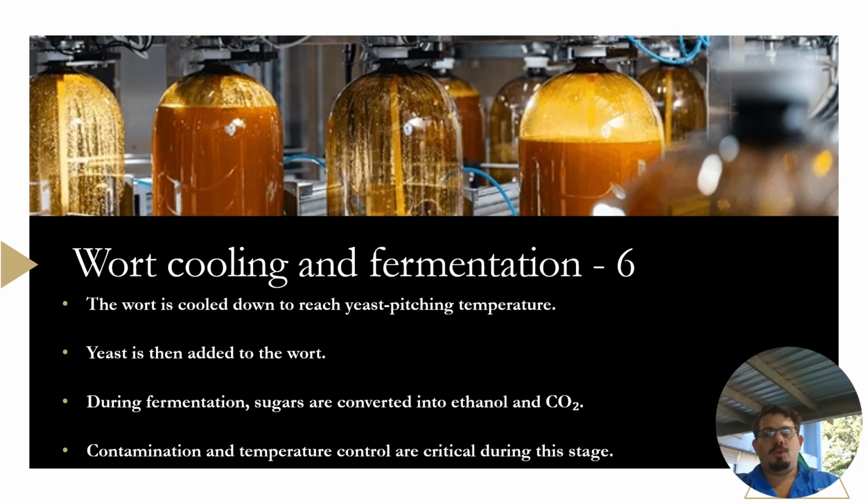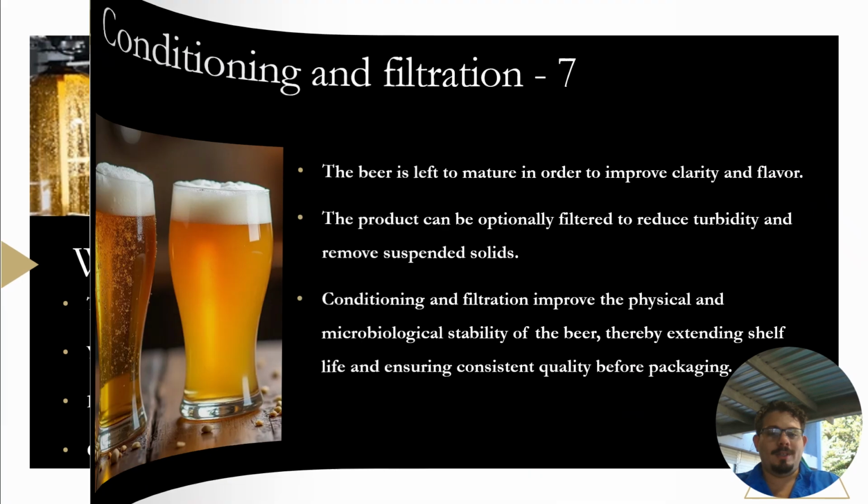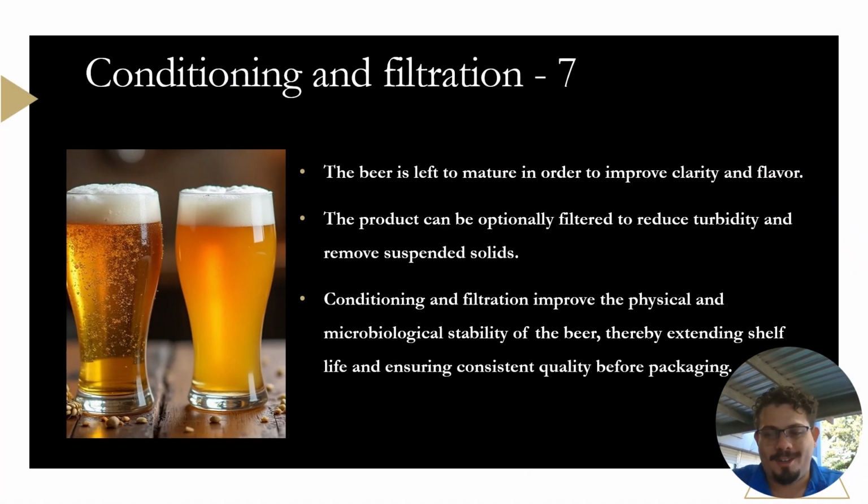Now we can move on to the final step, which is known as conditioning and filtration. In this step, the beer is left to mature in order to improve clarity and flavor, and the product can be optionally filtered to reduce turbidity and remove suspended solids.